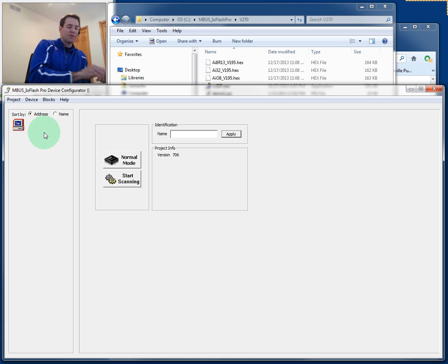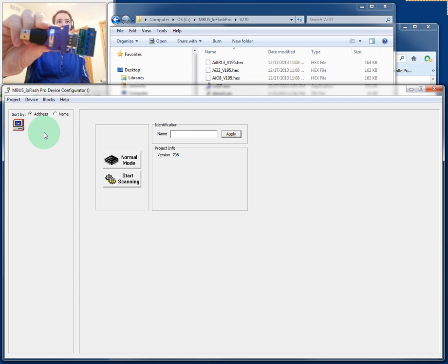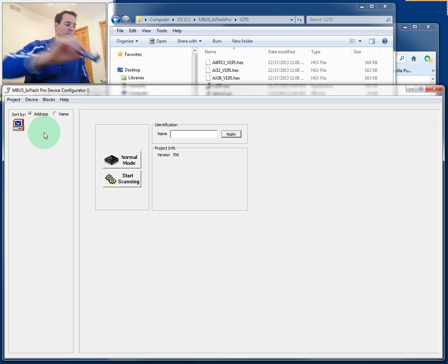You could also use a USB to 485 converter, as I mentioned before. That guy looks like this. On one end, it's got the USB style connector. On the other end, it's got screw connectors for the RS-485 network. And this is powered through the USB cable. So if you're going to use this one, you just plug the USB into your computer and then wire the 485 into the device from this side. But as I said, we'll use the Grid Connect Net 485 device for this demo.